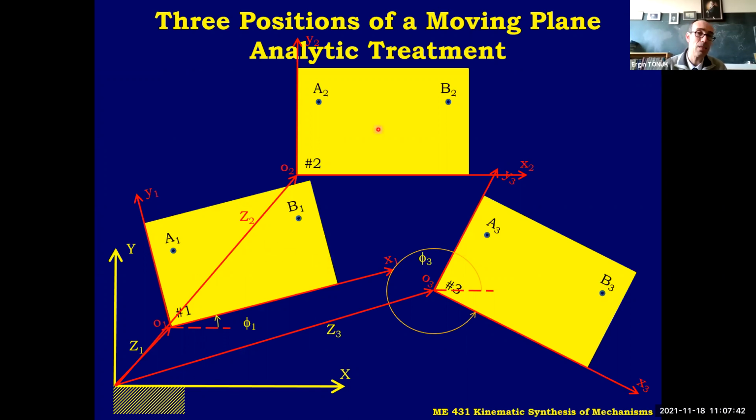However, these 3 positions define a pole triangle. The pole triangle has certain properties. We have the image pole triangle. We have the ground point. We have a limitation on the shortest crank. Or we may choose this point in such a way that its 3 positions are on a straight line, so that you can place a slider to B1, B2, say B3 is somewhere here.